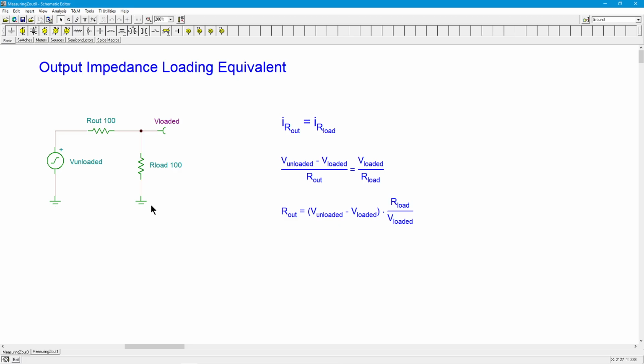Well, no big deal. Whether it's peak or peak to peak, however you want to do it, you can do it. The other nice thing about using a scope is, if you're doing a wide-ranging plot on this, you can also see what the phase shift is, so that can be handy. The math is a little bit more involved, obviously. I'm going to look at this strictly as a middle of the spectrum kind of thing, where everything is assumed to be resistive.